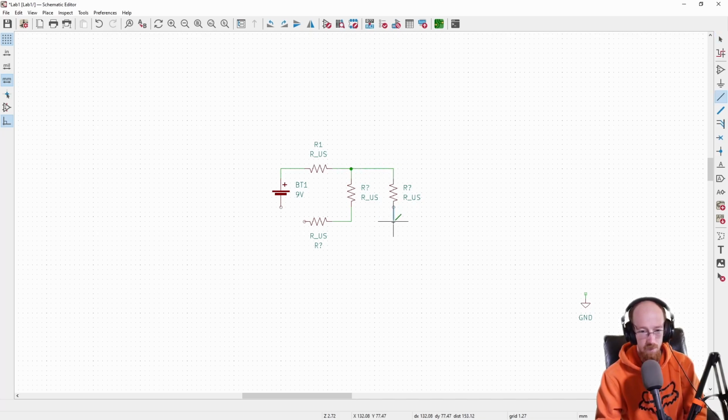Like so. Okay, so let's say that this is our circuit. And we technically do not need to deliberately notate a ground, but we'll put a ground here just so it's extra clear. This is where we're going to say ground is at, but this is just a reference. Remember, this circuit will work whether or not we have this ground symbol defined. Now, simulation-wise, I think it requires you to have a ground, but in reality, this is just a point we agree is 0. So with these, you notice these aren't annotated.